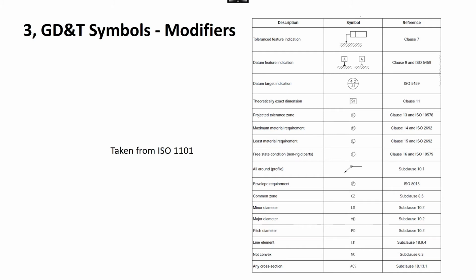Sometimes you can allow manufacturers to inspect components in their clamped state. Sometimes you want to inspect them in their free state. And depending on how they've clamped the parts, sometimes when you unclamp the part, the component can go out of flat, or it can move and things like this. So generally speaking, I would inspect most components in their free state, because that's how you're going to assemble them, unless they're very thin and you're going to clamp them on assembly in a similar way that the manufacturer is going to clamp them when they machine the components, for example.